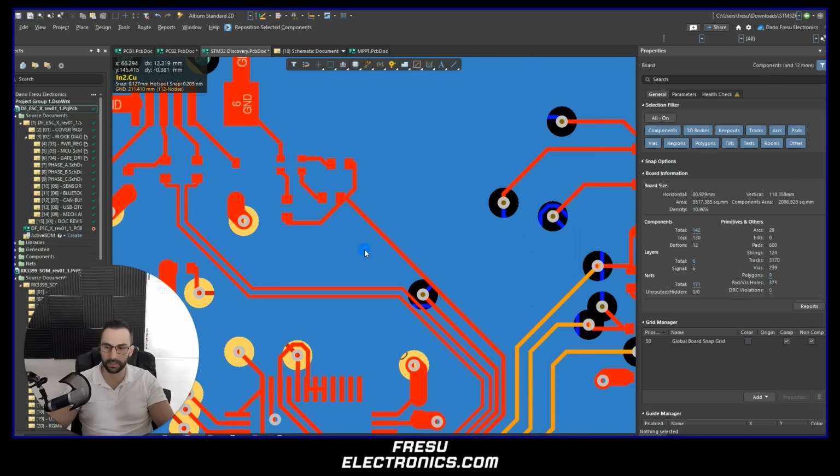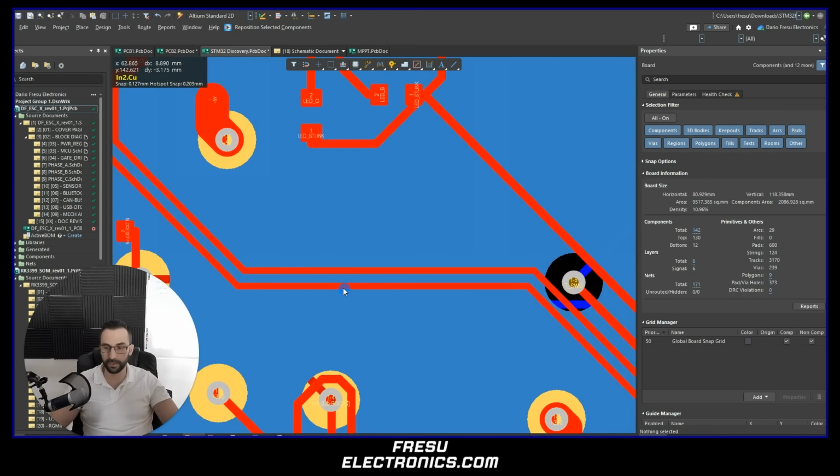So that there's a match between the source and the load. And you want to keep this the same throughout the whole propagation of the signal. So if, for example, you choose signals like USB, LVDS, PCI Express, and all these more sophisticated signals, you want to then make sure that the impedance is correct. And this you typically find either in the datasheet of the manufacturer of the IC. You can Google it and find immediately what impedance you should use for the signal traces. And then calculate what is going to be the width based on the impedance.